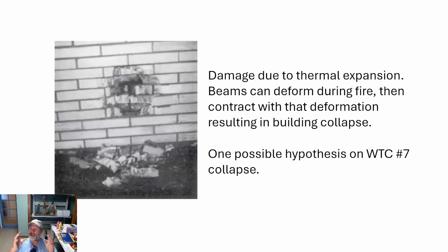So what happened there that's kind of interesting is because of the nature of the fire, its progression, you had these beams heat up. And they underwent some plastic deformation. And because you had the combined heat expansion as well as plastic deformation, it may not have pushed as much on the supports for the girders. But what happened during the cooling process after that fire had moved on, and this is most likely what happened with that structure, is it actually pulled those girders back.